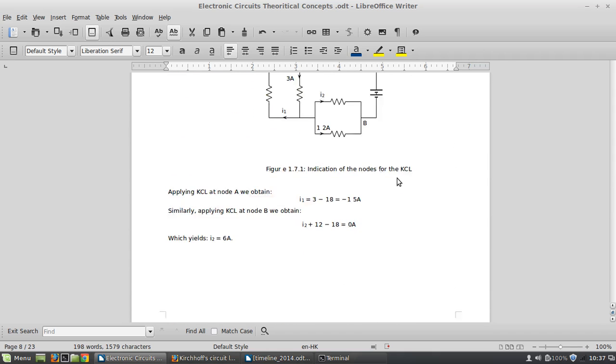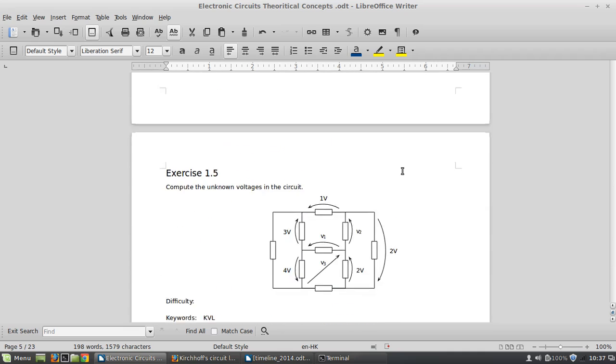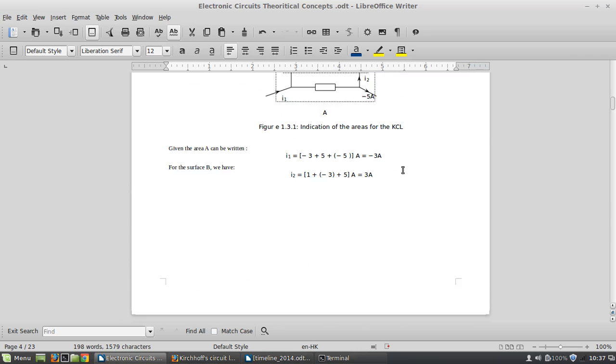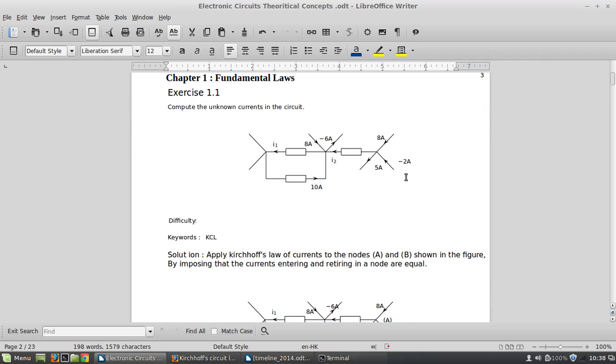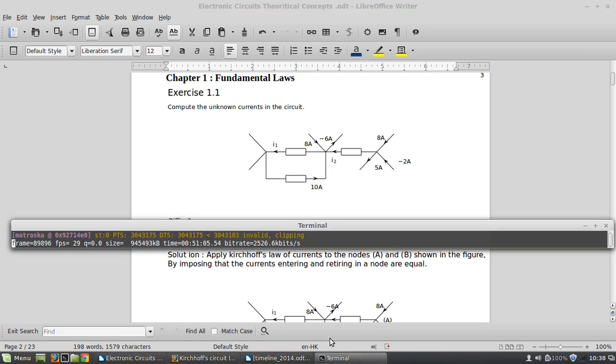Alright, so you can check out here. For I1, I divide the voltage by the resistor, right? You can check that the voltage is the same as 4 volt using the loop. Also find I2, which is the division from this current that will be flowing, something like 3 minus this current, which will be this current, right? And lastly, for the voltage, it will be the current times the resistor, and lastly for V2 we will use the KVL, and the same flows here. Lastly you have the power, which is also the product of current and voltage. Alright guys, so that's it for